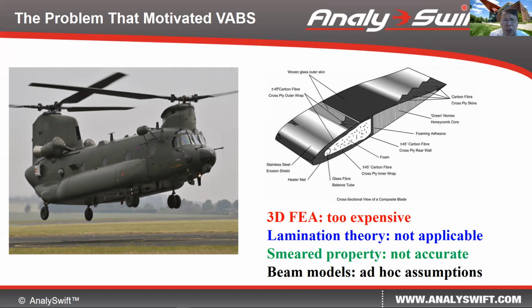Usually, a blade could be a few meters long, half a meter wide, and a few inches high, and it could be made of hundreds of layers, both the skin and also the spar, because each layer is about 0.1 millimeter thick.